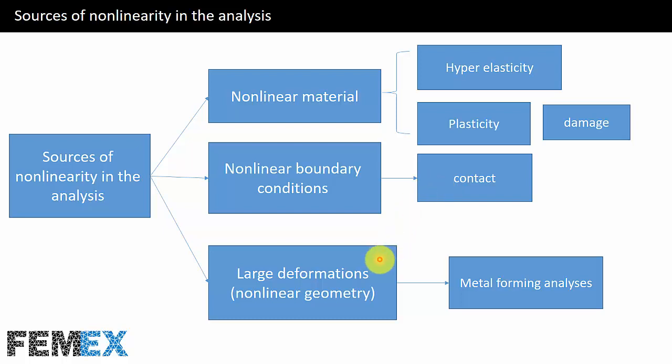And for large deformations, I can give you this example: metal forming analysis, like deep drawing, direct extrusion, and reverse extrusion, for example, or forging processes. All of these processes have large deformations, and so all of them are nonlinear.